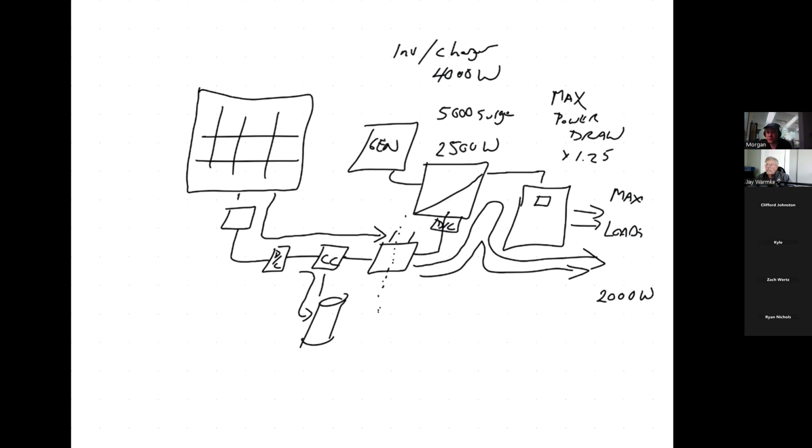And these things can have automatic settings where if your battery drops below, say, 20% or 30% or 40%, whatever you set it to, the generator will kick on and it will recharge the battery until it gets to whatever set point you've set. And those are there for the backup on cloudy days and extended storms and stuff like that. Just an added thing. So what I'm trying to point out here, though, is you size your inverter based on the maximum power draw in a standalone system.